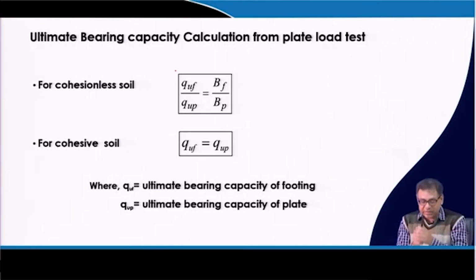Okay. And as I mentioned, when you are doing the plate load test, you are removing the soil and then placing the plate. So, actually the bearing capacity that you are getting from the plate load test, the second term contribution is not there. It will be the first term, or if it is a cohesive soil, only the third term will play into the picture, because it is a surface footing, since you have removed the soil from your pit. So, surface footing and C is 0. If only C is present, then for a surface footing phi, the third term will be 0, only the first term remains.